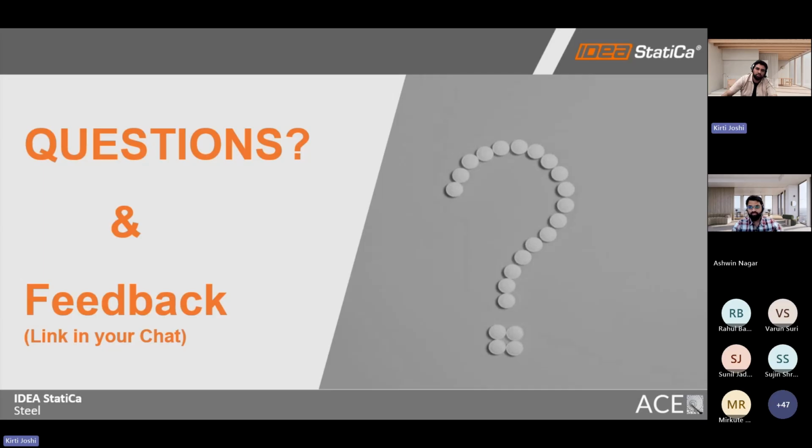Basically, you need to verify whether you have exported that member from the analysis software or you have just created it in IDEA StatiCa itself. Like, have you exported it using the Checkbot feature from STAAD, using the BIM link like ETABS or STAAD or another software? Basically, it depends on different analysis. It performs the GMNIA analysis, geometrically and materially non-linear analysis.